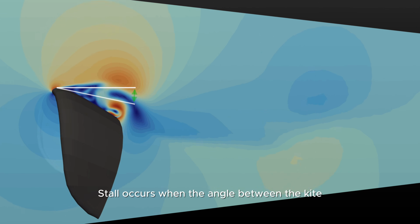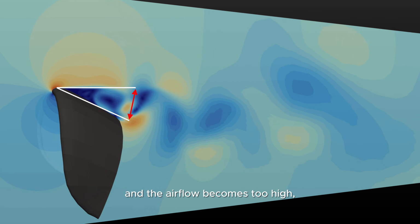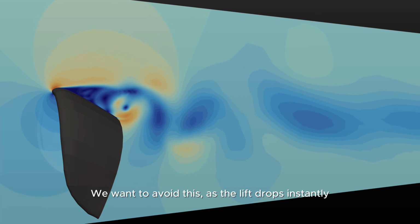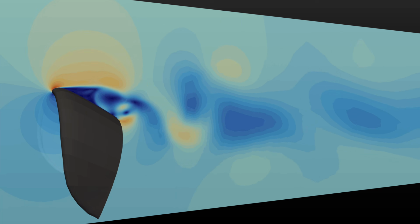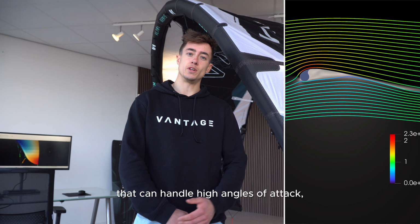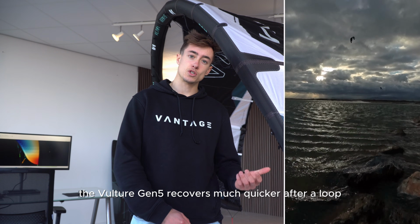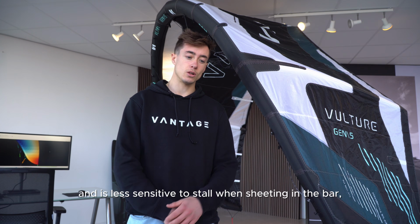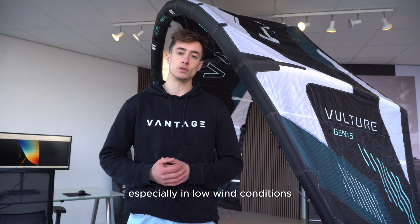Stall happens when the angle between the kite and the airflow gets too high, and the air can no longer follow the shape of the kite. We want to avoid this, as the lift drops instantly. By choosing profiles which can reach high angles of attack, the Vulture Gen5 recovers much quicker after a loop and is also less sensitive against stall when you sheet in the bar, especially in low wind conditions.